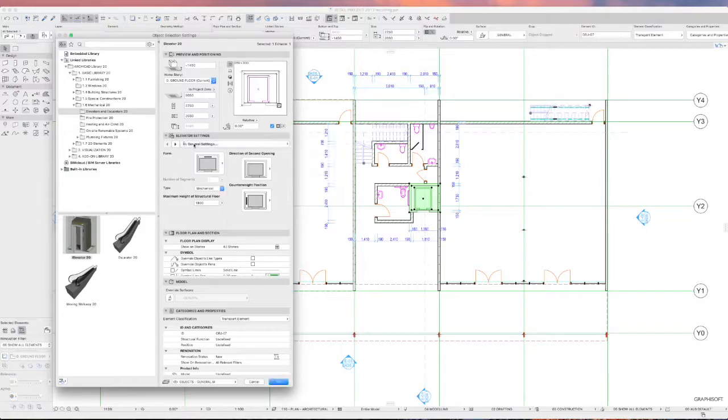Main settings, if we just start with general to show you a few things, the main one is the form. You can change your form to segmented shapes, which we don't want. Just a rectangular shape is more normal. And if you've got a second opening like a back door, you can set up the side door, whether the extra doors go on the sides, side 1, side 2 or the rear. And the counterweight position: whether your particular elevator has got a counterweight, or a monospace motor drive would take the place of a counterweight, being either on either of the sides or at the rear.